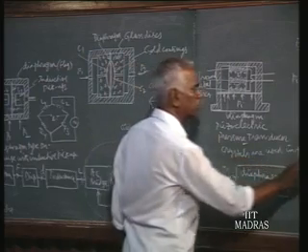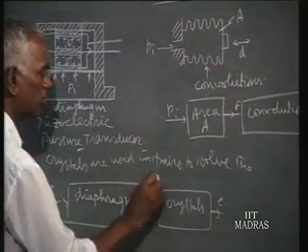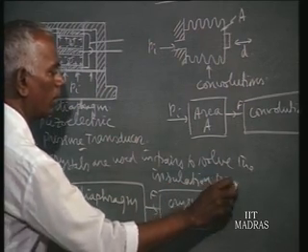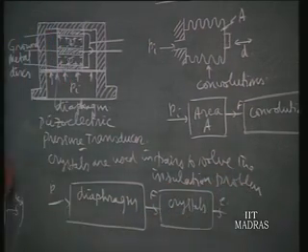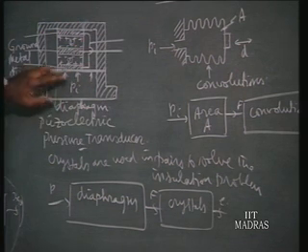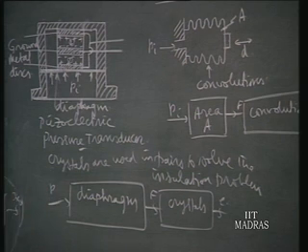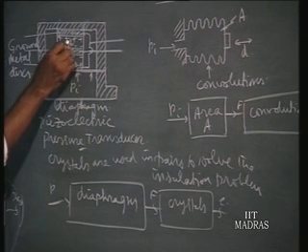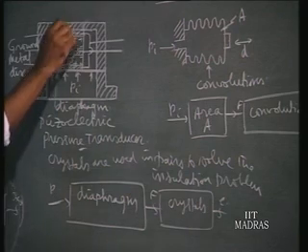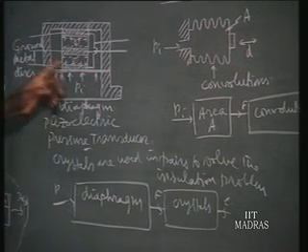Crystals are used in pairs to solve the insulation problem, because this whole frame will have only positive charge. The negative charge is inside, so it is already insulated. If you use only one crystal, the bottom portion will have negative charge but the top will have positive charge, and in between, in the casing itself, you have to insulate.